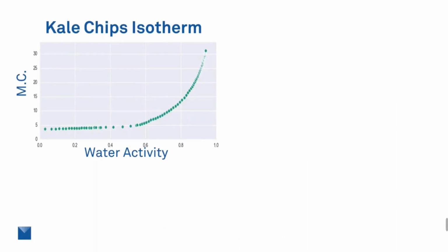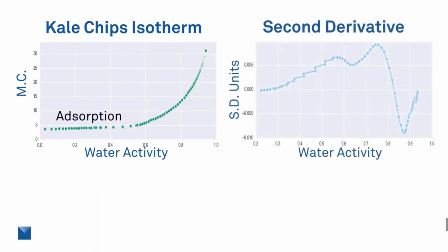If you're just visually looking at this, you could probably guess where that loss of texture is. It's going to be an inflection point in that trace where we see the adsorption properties really increase, a large intake of moisture content. But it is a little tricky to exactly identify that, and it's important that we do. So the simplest thing is to go through and do a second derivative evaluation on that slope. Basically it evaluates the slope to see when the change happens in the slope. It's very easy.